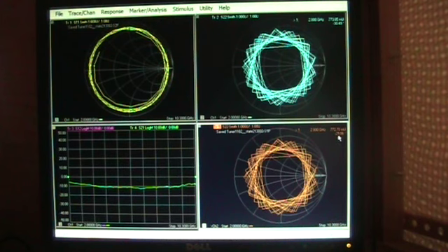The other thing to note here is the relative phase. We've got 29.86 degrees on the one port, the gamma source. You see that it's 30.49 degrees from the 2-port measurements. These are very, very similar to one another, and that should be comforting to us to say, okay, we've probably got all of the calibrations right. These are nearly matched up. There's a subtle difference between the two.